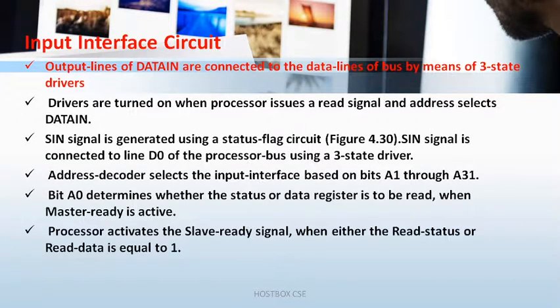Then we see the input interface circuit. Here the drivers are turned on when the processor issues a ready signal and the address selects the data in. Also the SIN signal is generated using a status flag register, and the SIN signal is connected to line D0 of the processor bus using a 3-state driver. And also the address decoder selects the input interface based on bits A1 to A31.